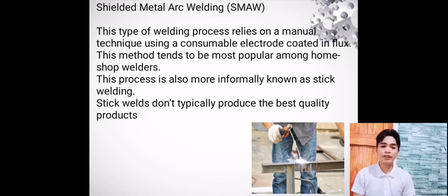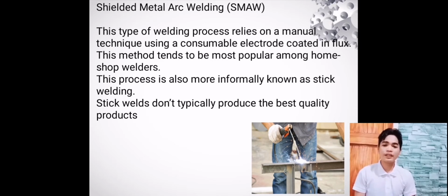The heat from the welding arc is intense and extremely concentrated. It immediately melts a portion of the workpiece and the end of the electrode. It is the most popular method because of the versatility of the process and the simplicity of the equipment and operation.